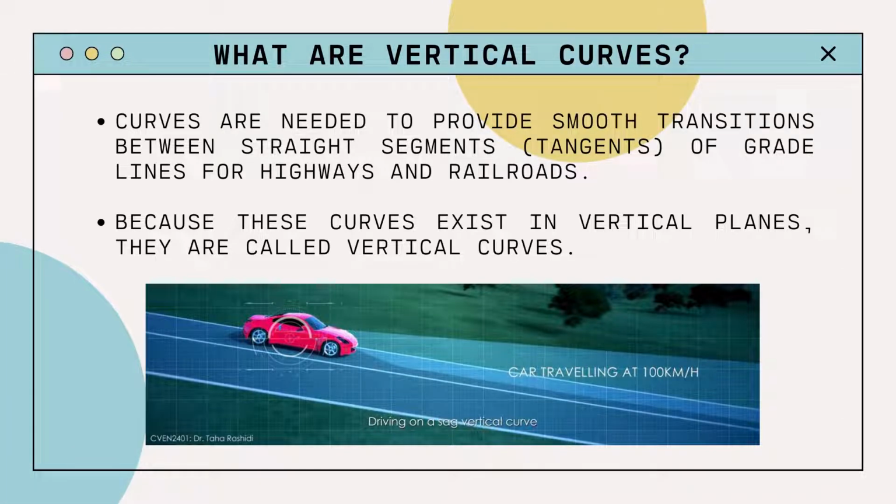What are vertical curves? Vertical curves are the second of the two important transition elements in geometric design for highways, the first being horizontal curves. A vertical curve provides a transition between two sloped roadways, allowing a vehicle to negotiate an elevation rate change at a gradual rate rather than a sharp cut. Because these curves exist in the vertical plane, they are called vertical curves. The design of the curve is dependent on the intended design speed of the roadway, as well as other factors including drainage, slope, acceptable rate of change, and friction. These curves are parabolic and are assigned stationing based on the horizontal axis.